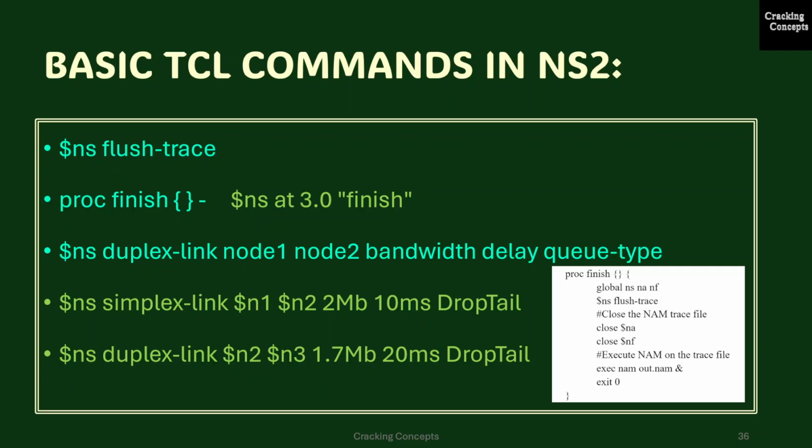Next, we will see the function proc finish. So here, all the post-simulation processes are specified. A sample code is given here. Here the word proc defines that it is a procedure. The name of the procedure is finish and it doesn't have any arguments. The word global means that we are using variables declared outside the procedure. The TCL command close